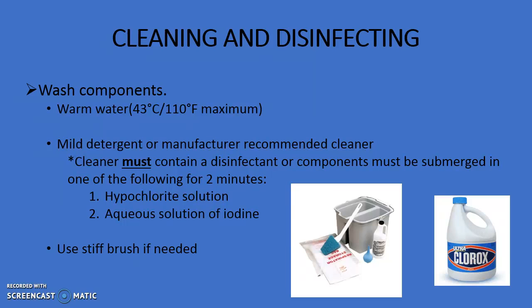Wash the components in warm water with a maximum temperature of 43 degrees Celsius or 110 degrees Fahrenheit with a mild detergent or with a cleaner recommended by the manufacturer. A stiff bristle brush, not a wire brush, may be used to aid in the removal of dirt. Be careful not to push too hard on the valves. They are made of less durable material and can be damaged.